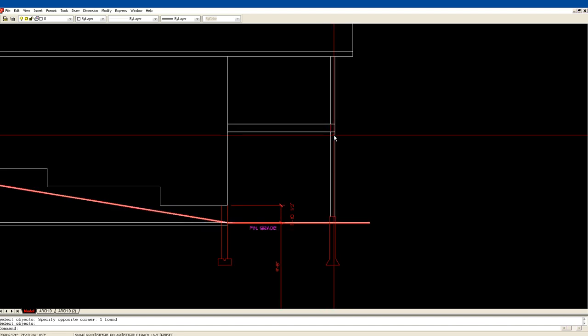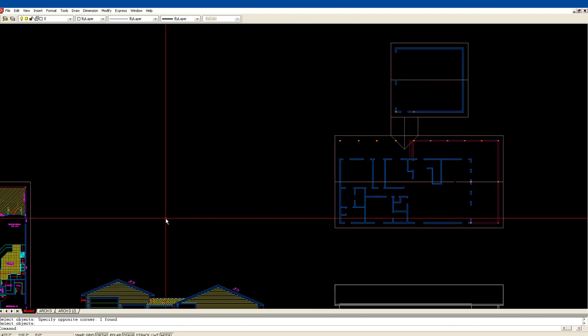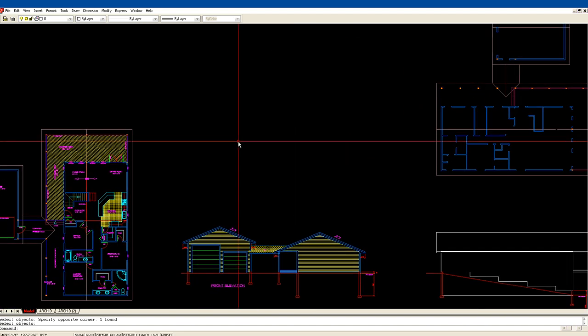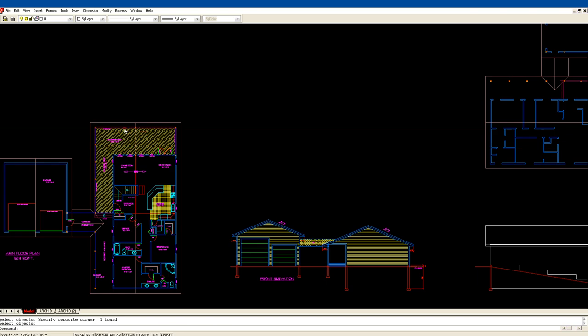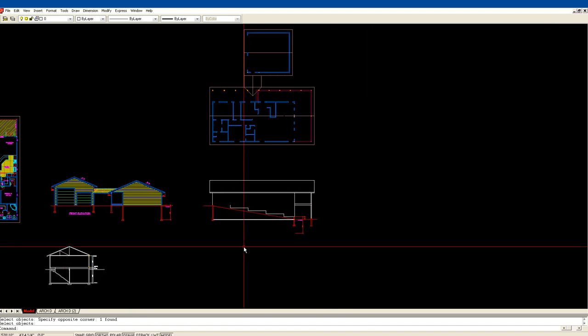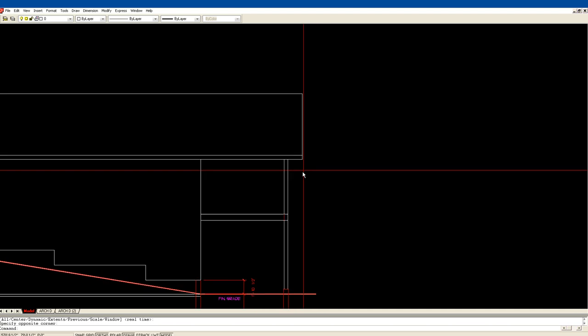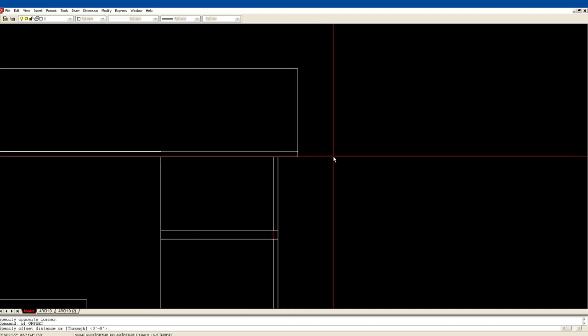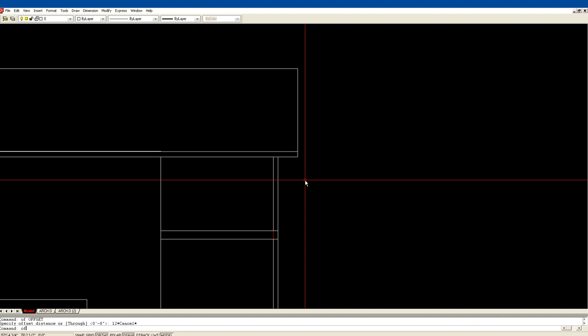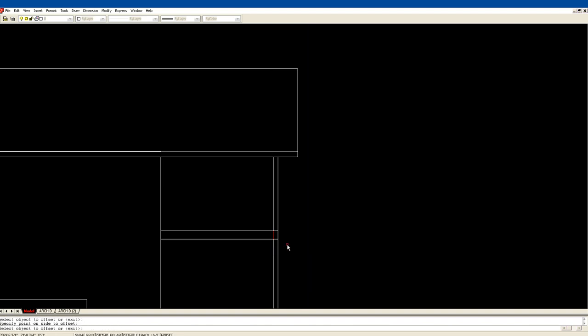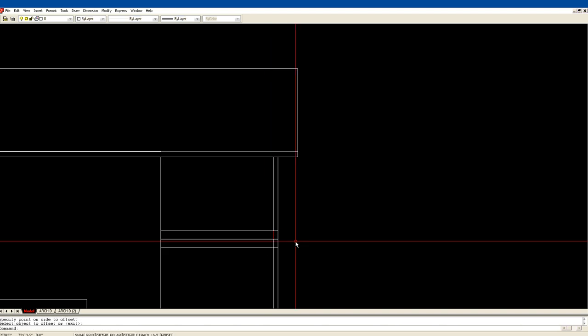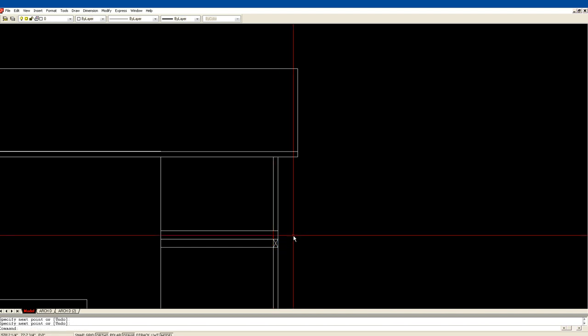What we're missing is a beam. So when we go here to the construction of the deck, we are going to have a beam that runs right along here, and all these floor joists are going to sit on top of it. We're just going to zoom in here, and again, we haven't sized the beam. I'm going to offset 10 for now. I'm just going to draw a line from there to there, and from there to there. So that's a beam.